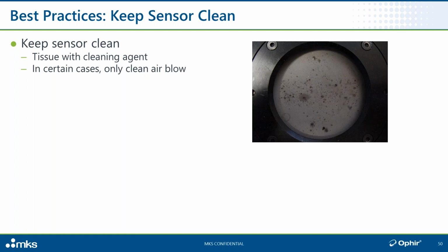Here you see a sensor. The sensor apparently must have had some organic stuff splashed on it, but that stuff didn't get cleaned off, and on the next exposure to a laser beam, it got burned on. This can't be cleaned. That sensor needs a pretty expensive disc replacement. Had it been cleaned before exposing it to another laser beam, it probably could have been cleaned off very easily with a soft tissue and some suitable cleaning agent.